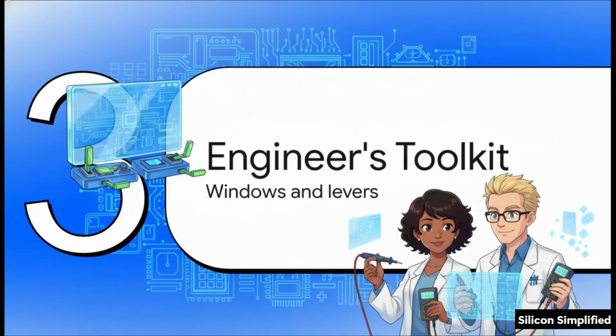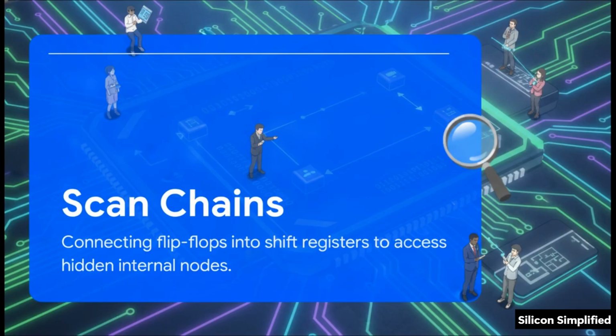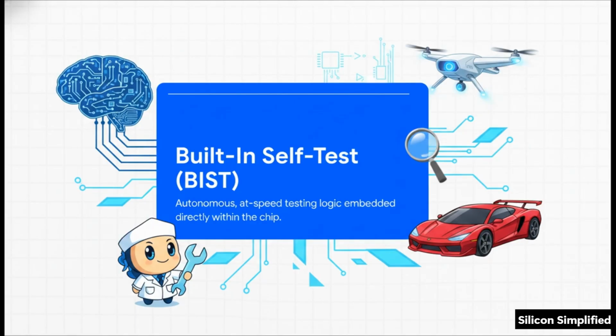Which brings us to Section 3, the test engineer's toolkit. So how exactly do engineers build those windows and levers in real life? The first major tool they use is the scan chain. See, in highly integrated circuits, you simply can't access internal logic directly through the external input and output pins. Scan-based testing solves this problem by taking internal flip-flops and connecting them together to act like shift registers whenever the chip is put into test mode. This effectively turns deeply buried, totally hidden internal nodes into a chain of readable, controllable data, all without needing any invasive physical probing.